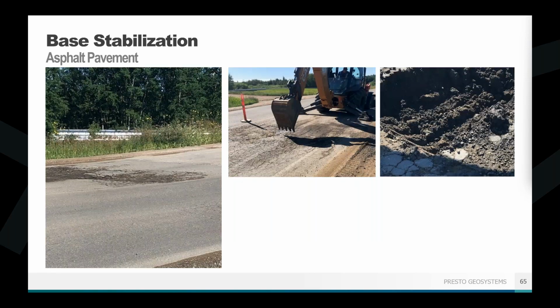Another similar type of project failed, in this case, a very small location of asphalt. And so they wanted to just replace a small little thing, and that's totally fine. Rip out the failed asphalt. You're going to put the GEOWEB system in underneath it, and then put new asphalt on top. So it doesn't have to be a big project. It can be very small. It can be very localized, and the GEOWEB system still gives you that benefit. It doesn't have to be hundreds of miles of roadway to be a benefit. It can be a very small location.